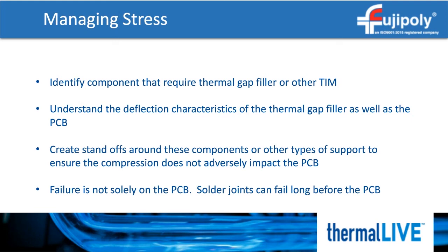Creating standoffs and supports around the components that will require a high-performing gap filler is always a good idea. This is the simplest way of reinforcing a PCB. Failure of the PCB is not solely due to the solder joints. Solder joints are rigid, but PCBs are not. Having something rigid soldered onto a substrate that will flex means something will fail if the deformation is more than what the solder joint can handle.